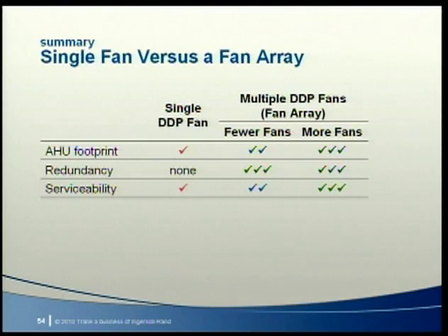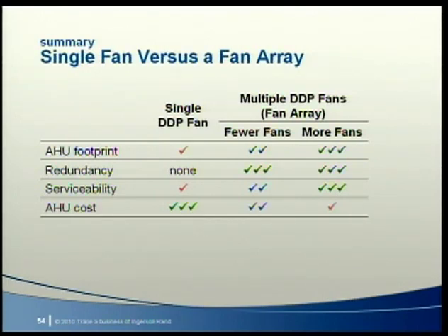Another benefit of using a fan array is easier serviceability. When multiple smaller fans are used in the same array, the fans or motors are lighter and easier to replace if necessary. Using a single fan wheel will typically result in the lowest cost air handling unit. When a fan array is desired, using fewer, larger fans will typically cost less than using many smaller fans.